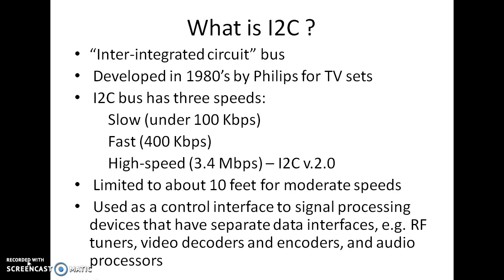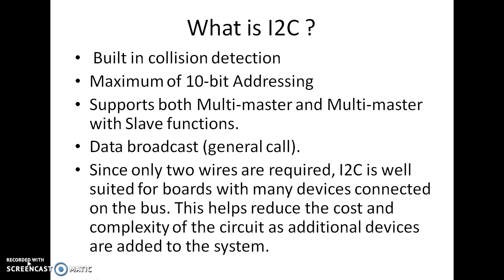It is used as a control interface to signal processing devices that have separate data interfaces, for example RF tuners, video decoders and encoders, and audio processors. It also has a built-in collision detection mechanism. The addressing used is a maximum of 10 bits. It also supports multi-master and multi-master with a slave function, and it has a data broadcast general call function.